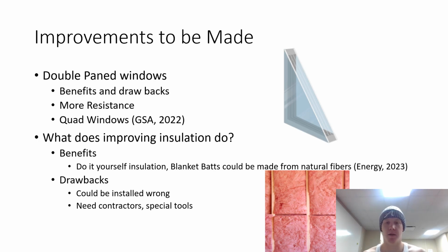In conclusion, I think there are many improvements to be made. The parameter that I thought was the best was parameter 2, but this cannot always be the case in reality. Some other things that you could change in a house that would be awesome would be double-paned windows. Double-paned windows are going to be much better than single-paned windows because they have a larger resistance network compared to just a single-paned window. A double-paned window would have 3 resistors instead of 1 resistor.